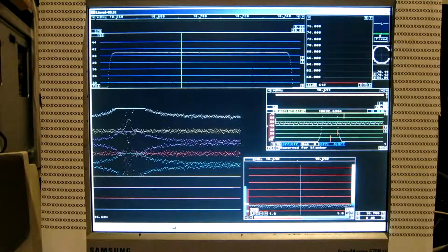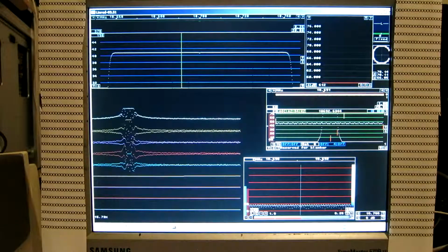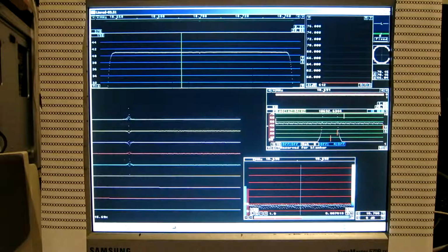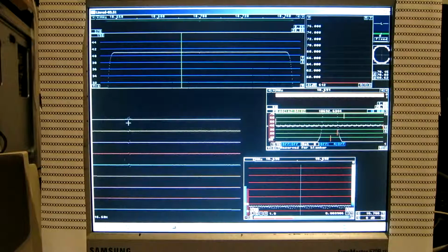I reduce the gain by clicking the minus box. And here is the peak amplitude. That's the maximum of a single pulse. And enable the smart blanker like that. And you can see the pulses are weaker, but the effect is not good at all. I magnify with a plus, that is 6 dB, 12 dB. The smart blanker does not work well here.